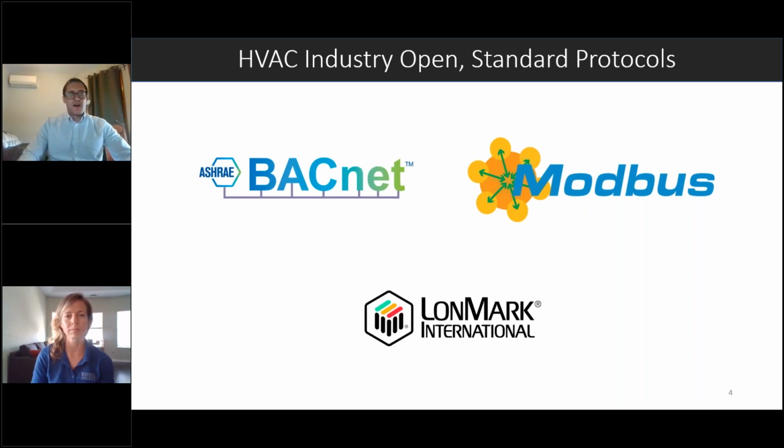That one's become the most prevalent in our industry today. Definitely you will see BACnet more often than any other protocol that I have listed here. But the other 2 are important to understand and be aware of. Modbus I see most commonly with third-party systems. A lot of times I'll see Modbus as a form of communication that boiler manufacturers like to use.